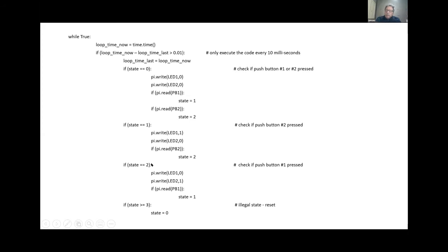And this will just process around, and only one of these blocks of code will actually be processed each loop. So I can have thousands of lines of code, but typically each loop may only be processing 10, 20, 30 lines of code. Hence I can get around these loops pretty quick. So that's a sort of non-blocking piece of code.